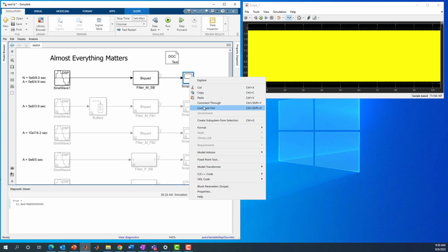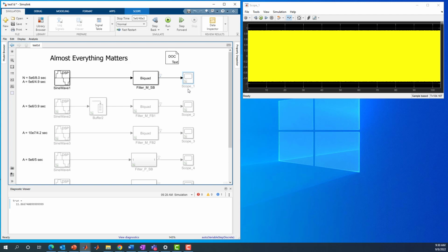If I were to disable the visualization and run again, you should get much faster times. Now, you have to be careful about doing that because Simulink can, in fact, optimize away the whole simulation if it senses that the results are not being used. So you have to pay attention to that. That's why I have the logging on the output. Sometimes when it's not logging, it'll just say, well, you're not viewing the signal, you're not computing with the signal, you're not logging the signal, therefore I don't need to compute that output. And so you have to be very careful that you're not fooling yourself when benchmarking.